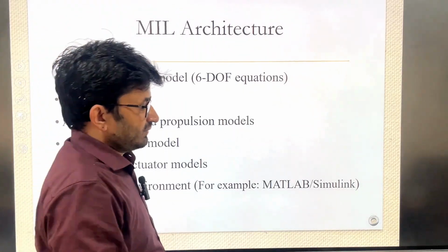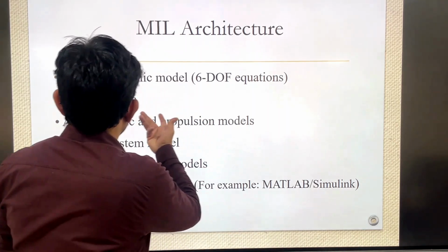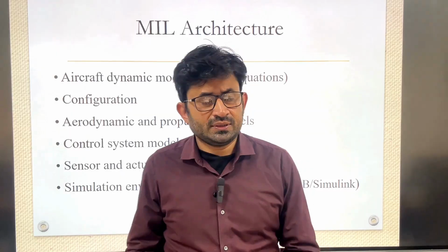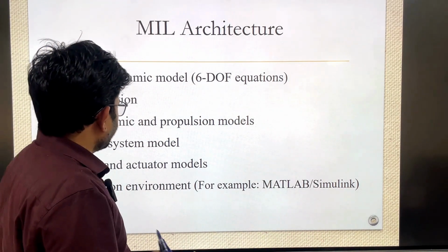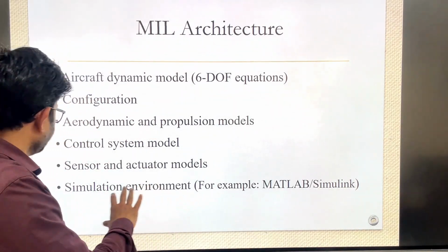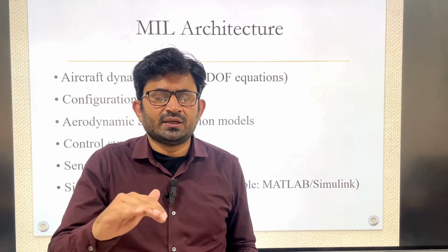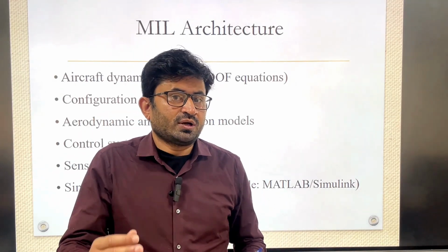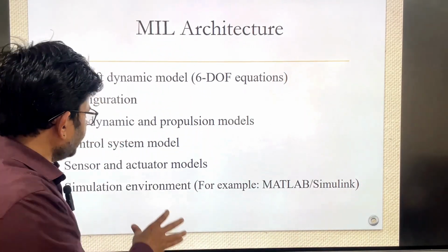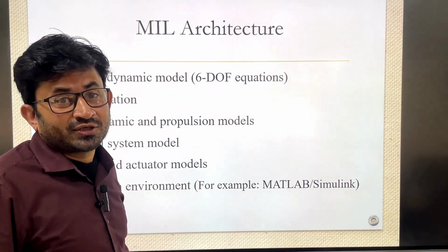And what is the typical MIL architecture? So the aircraft model will be there and the controller will be there. Two things are common, depending upon the configuration, whether it's multi-rotor, fixed wing, or hybrid. And then of course the aerodynamic model and propulsion model, control system model, and sensor and actuator models. Because in a simulation, during the MIL, you can model the sensor, you can model the sensor noise, you can model the actuator, first order, second order, all things you can do here. And of course, one environment you need, like MATLAB and Simulink, in order to do your MIL.